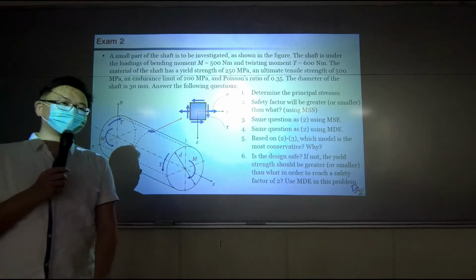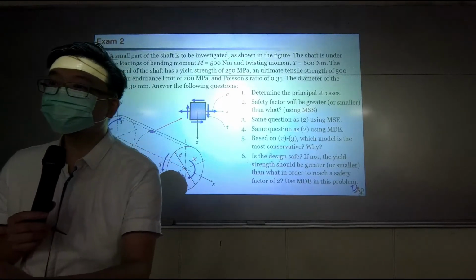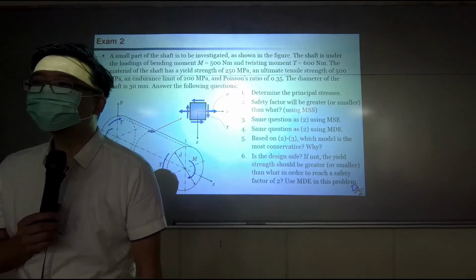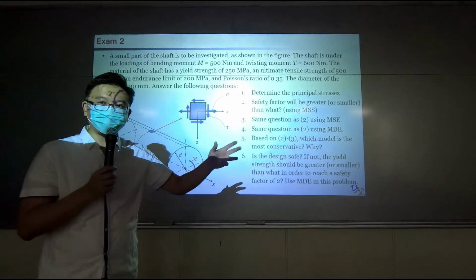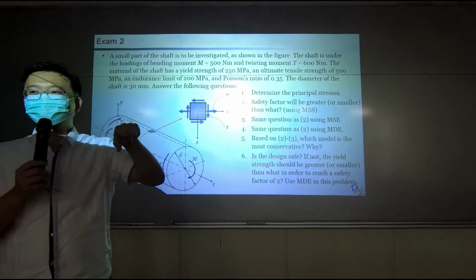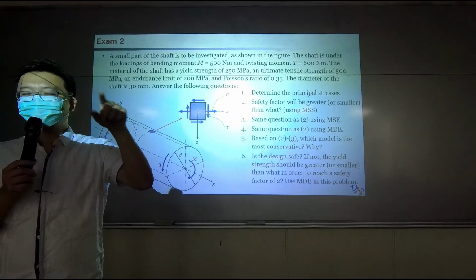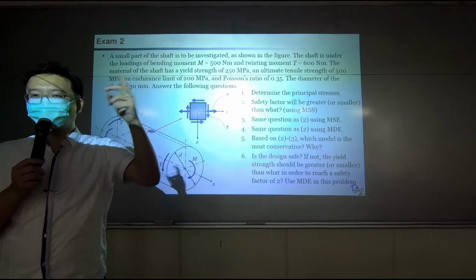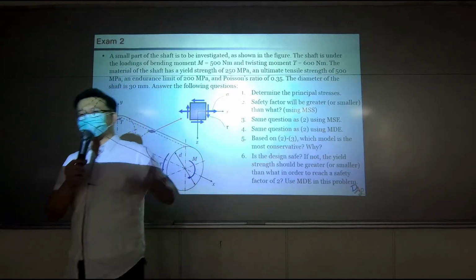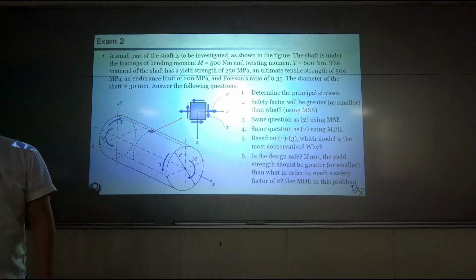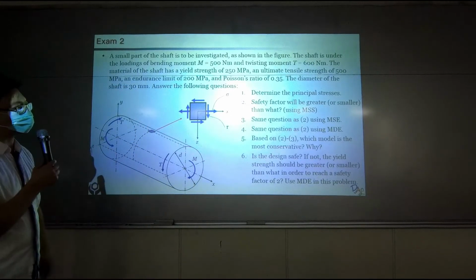Try it. So we can use the max stress model. Yes. Because in the model we have all the S, and S stands for the principal stresses. So that's why in the first small problem we need to determine the principal stresses. Very simple reason. Yes, thank you.